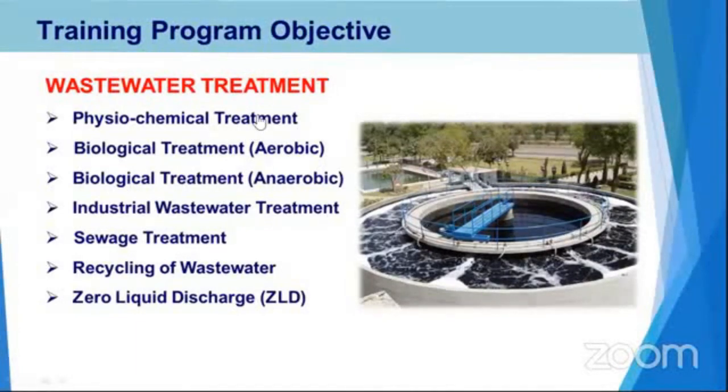If your temperature is high, you have to lower the temperature. If you have suspended solids, you have to remove them. In the denim industry of the textile, you have pumice stones. These need to be removed, like grit removal. These are the physical treatment.